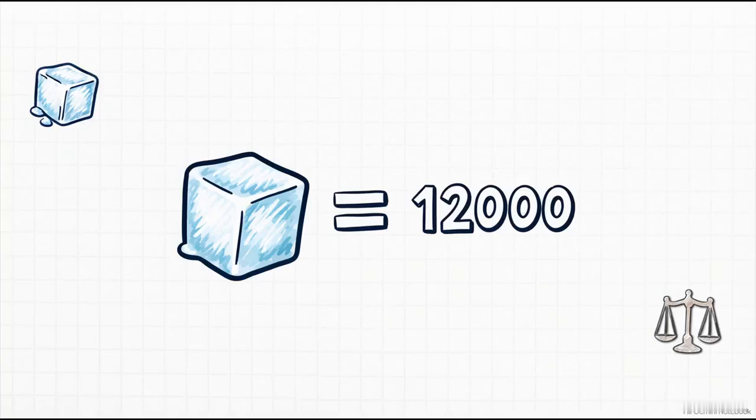Finally, Section 5, Measuring HVAC Capacity. So how do engineers actually size the heavy equipment needed to handle all of this moving, treated air? In an HVAC world, we use tons. But we aren't talking about physical weight here. We convert standard heat energy, BTUs per hour, into cooling tons simply by dividing by 12,000.